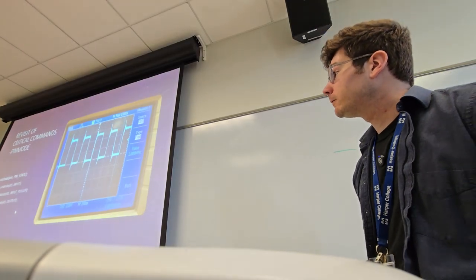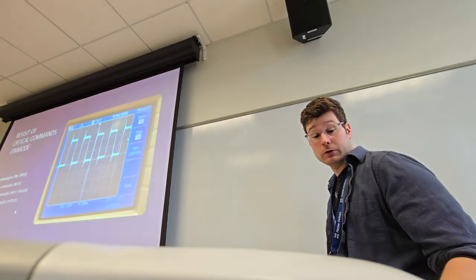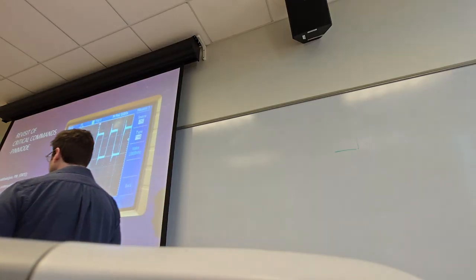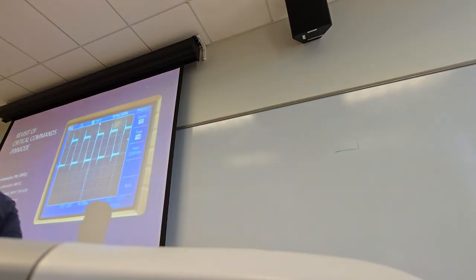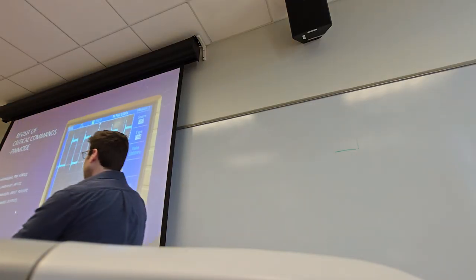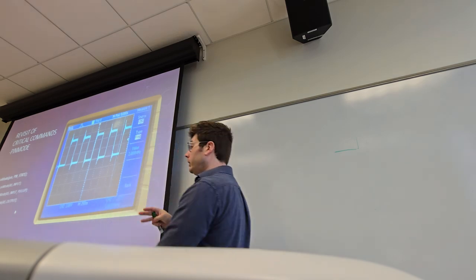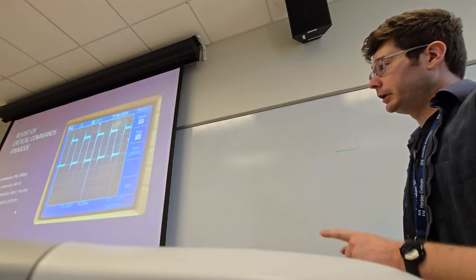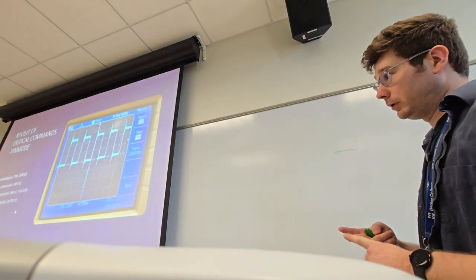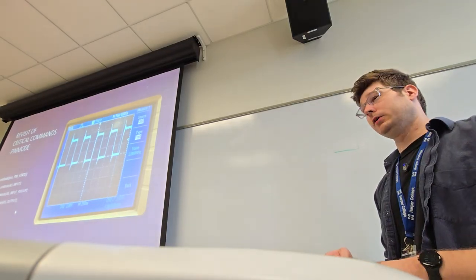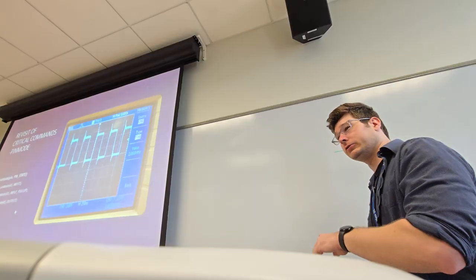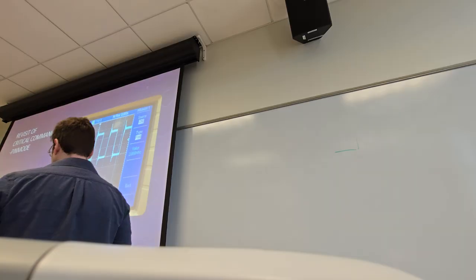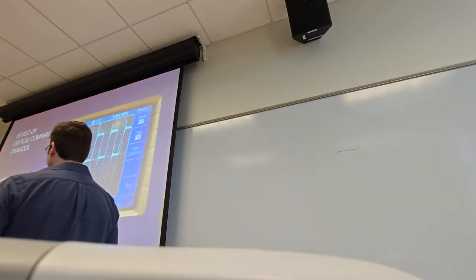All right, so first up is pinMode. I won't labor on this point too much. I know I brought it up a few times, but here's a great lookup for essentially the three different kinds of pin modes you can set up. We can do an input, we can do a pulled up input, which is a default high input, right? It's not floating when there's nothing attached to it. It is high when there's nothing attached to it. And we can set it as an output where we expect it to drive something.